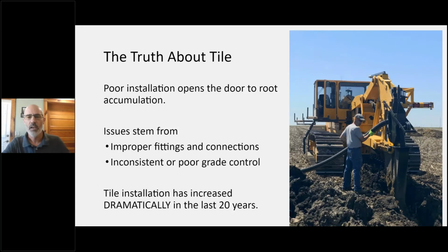Next slide, please. So the truth about the tile is most of the problems that we hear about come not from the fact that we're throwing the cover crops in there. It is how that tile is being put in. One of the new factors that came into play is that as farmers invested in tile, many farmers started doing their own tile. They're new to it, so they don't have a lot of experience. It doesn't mean that farmers themselves cannot install tile well. It just takes time to learn the ins and outs. When you talk to tiling contractors who've done it for a generation or two or three, you will find they can explain the issues.